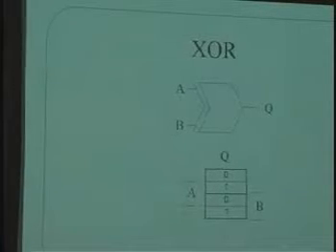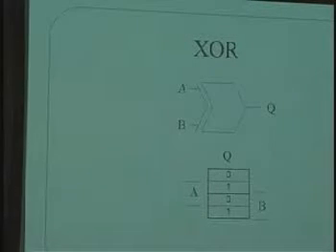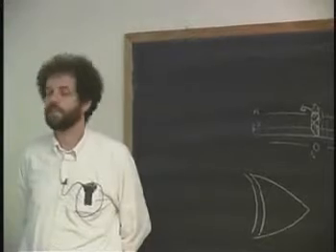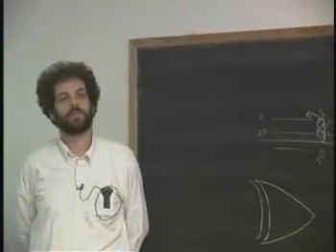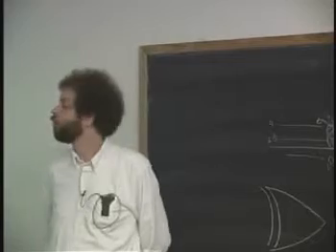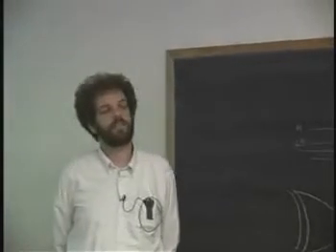There's also XOR. That's an exclusive OR. And typically the symbol for that looks like this, with an extra arc on the back of it. And it has a K-map form that is very interesting in that it looks like a checkerboard or a chessboard, where it goes dark, light. And whenever you see things that look like a checkerboard, the first thing that should go into your mind is, this looks like XOR. And why is that? Because XOR has this incredible characteristic.